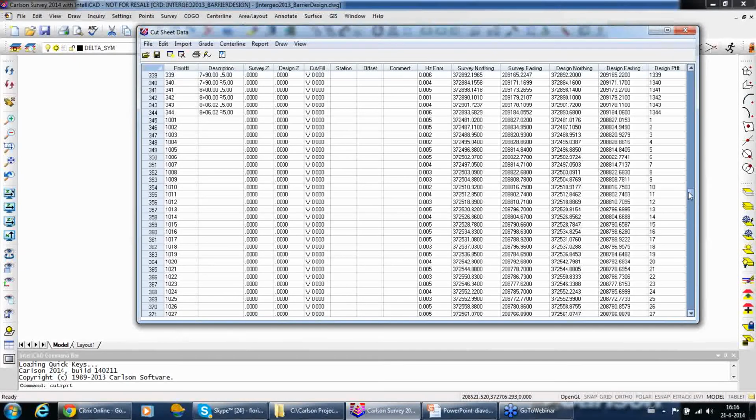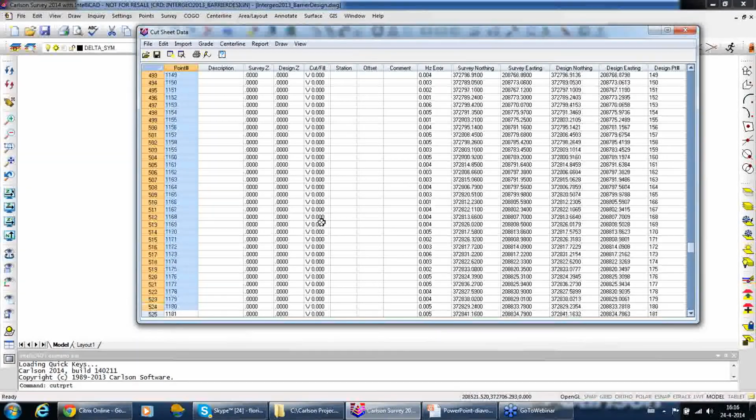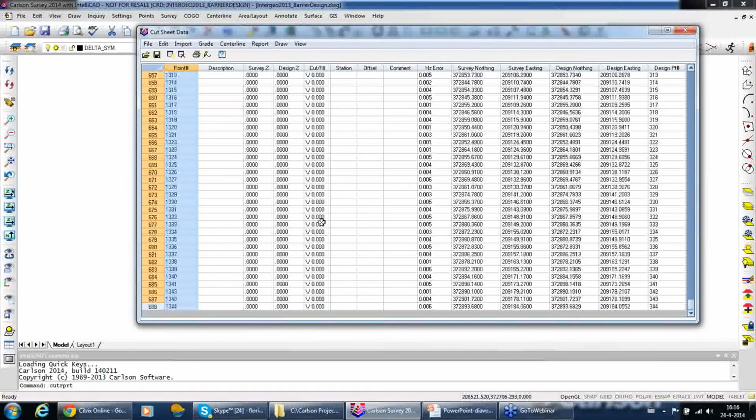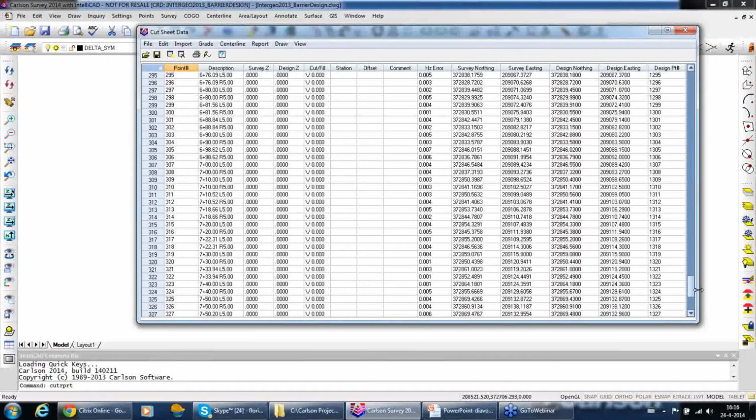Now before I start plotting this on the screen, I want to remove the second half, because of course if both are in there, then it means you would get a match from survey to design and from design the other way around again. So I'm going to remove one group of the points because now they're double. Okay, deleting the points. Okay, there we are.